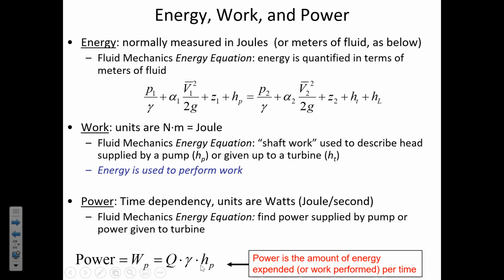The same kind of equation describes the amount of power that is generated by a turbine. But when we account for efficiency, there's losses, then that's when the turbine power equation and the pump power equation are a little bit different. Of course, in theory, there's a perfect exchange between the electricity that goes into a motor and the power that is added. But the reality is that when you add electricity to a motor, the motor heats up, and the majority of the losses are due to heat. But there's other things as well, like vibration and so on.